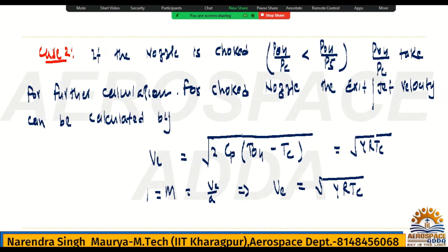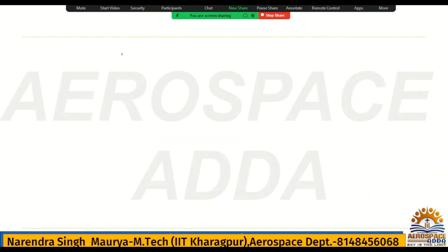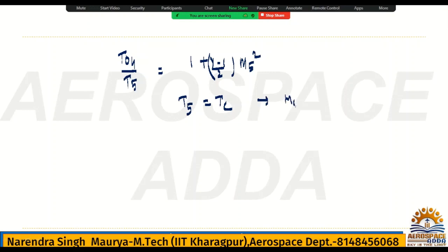So the last is what? How to get TC. TC is the critical temperature. How to get it? It is very simple. What is the formula of T04 by TC? See, T04 by TC, or let's say T04 by T5, better. So what will be T04 by T5? It is 1 plus gamma minus 1 by 2 into M5 squared. If I say T5 is equal to TC, choked condition, then what will be M5? It is 1. So T04 by TC is nothing but gamma plus 1 by 2.